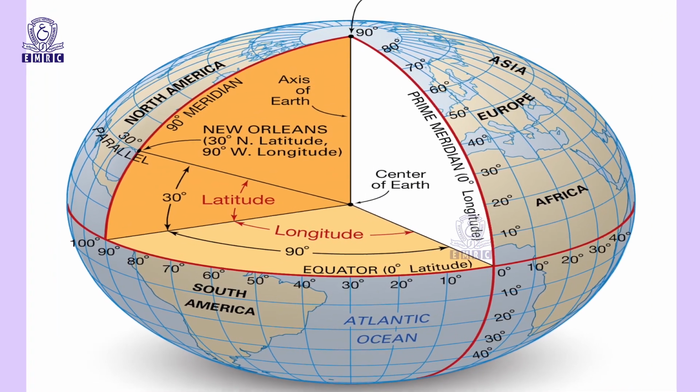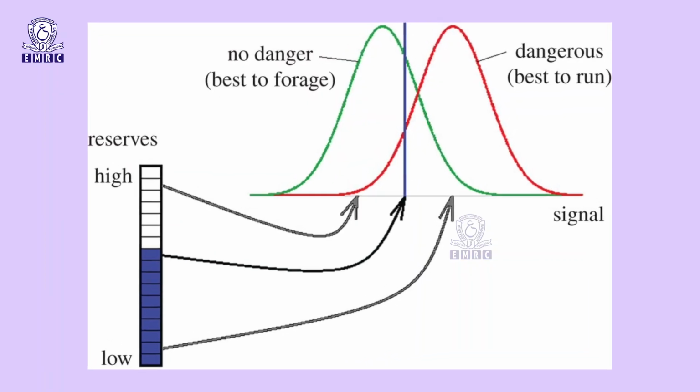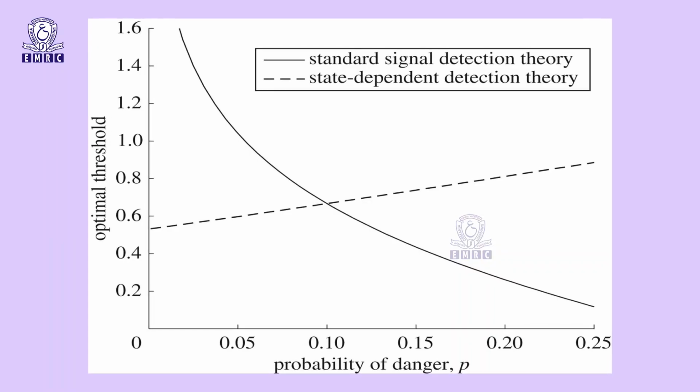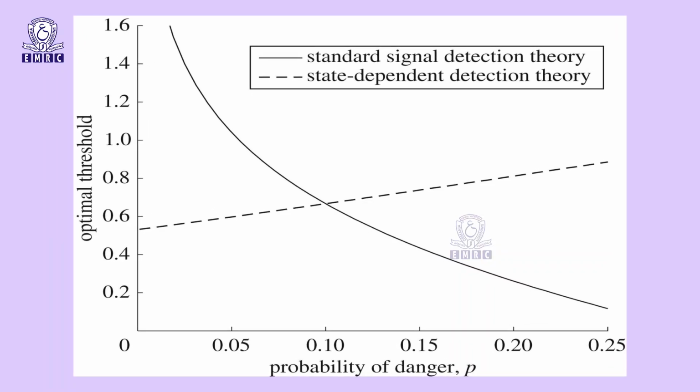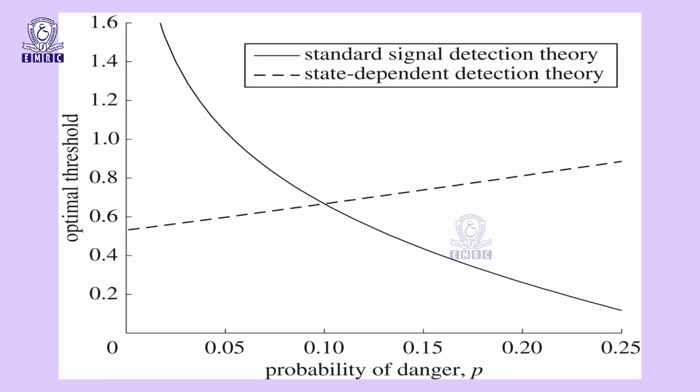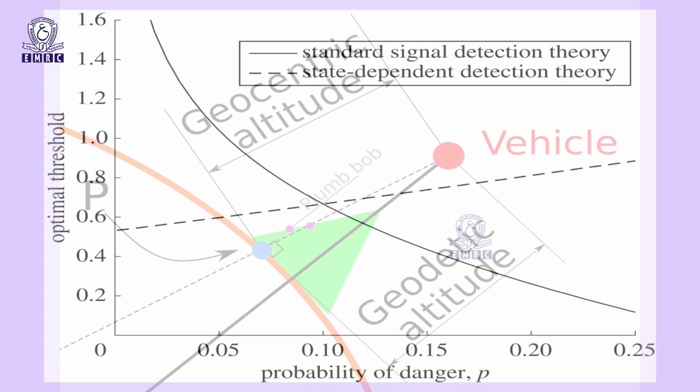With 5 satellites visible, it is possible for the system to automatically detect an erroneous signal. With 6 satellites visible, it is possible for the system to automatically detect an erroneous signal, identify which satellite is responsible and exclude it from consideration.